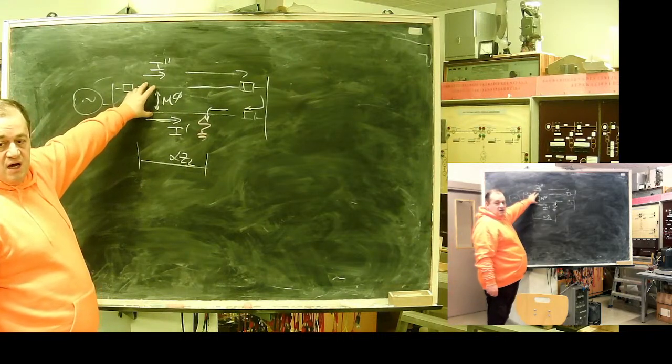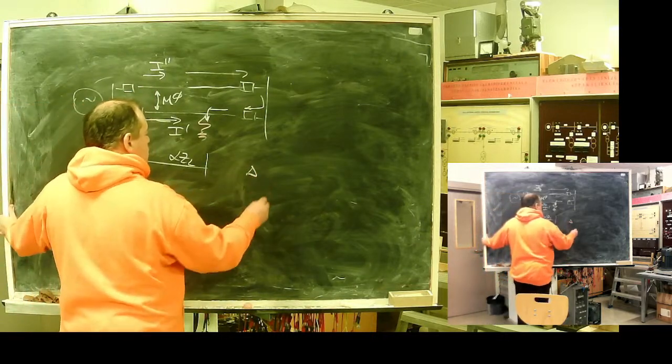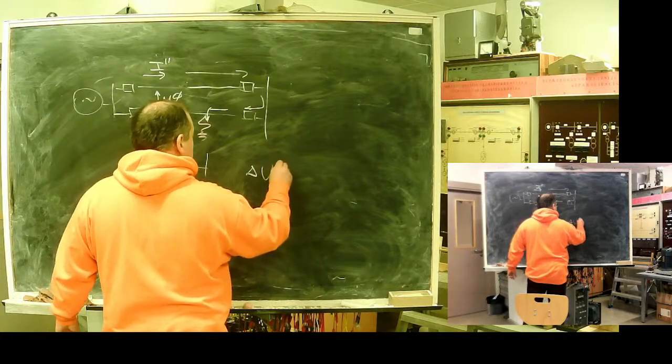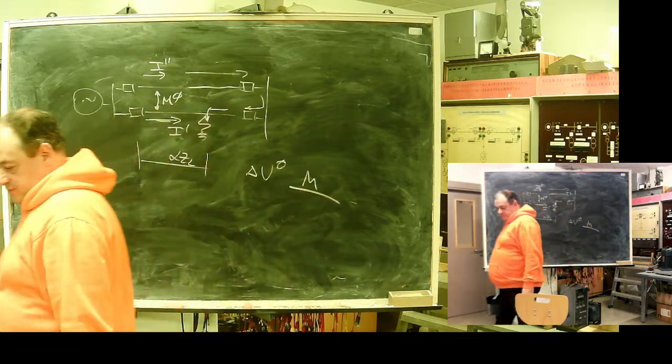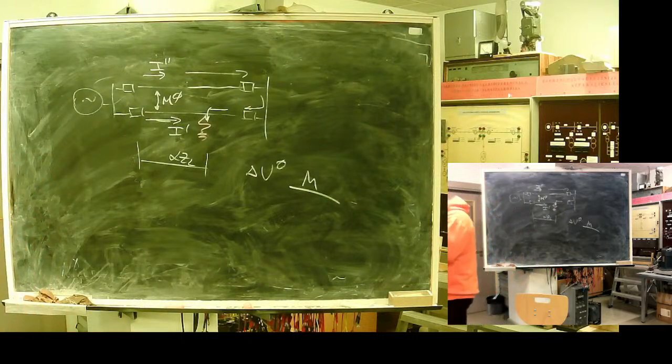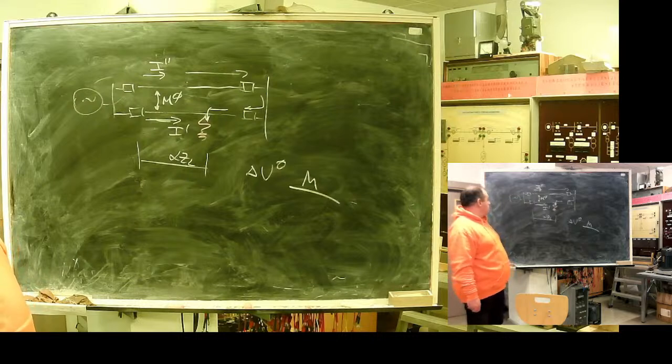But through this inductance, there will be an additional voltage drop observable to our protection as an increase in observable resistance.